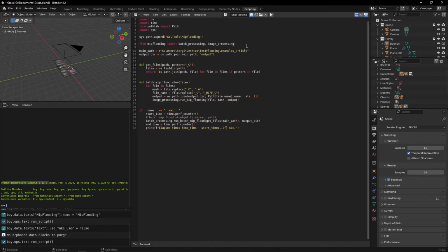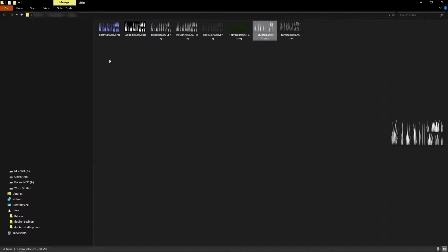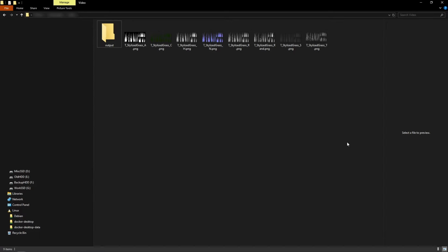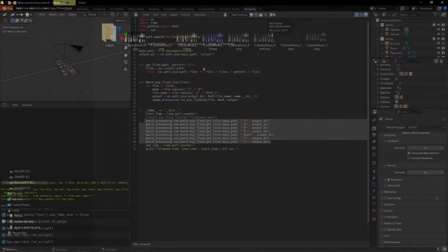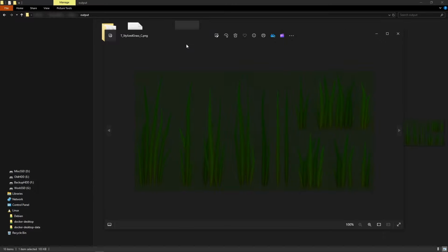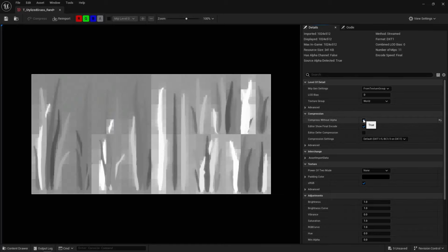Final step is to specify where my PBR passes are located on disk. Rename them so they contain the proper suffix. Tweak the script a little bit so that it processes all passes. And voila, run the script and images on disk should be flooded. You'll notice images are somewhat transparent still, but it's no biggie. The RGB channels are correctly flooded, so you can just get rid of that alpha channel or import images in UI without the alpha channel.